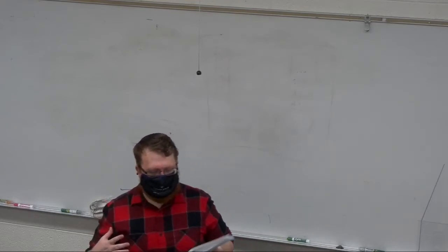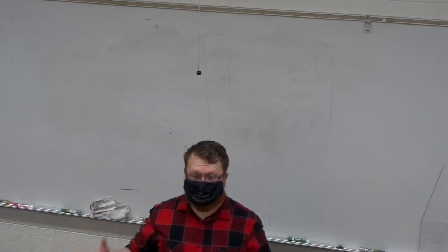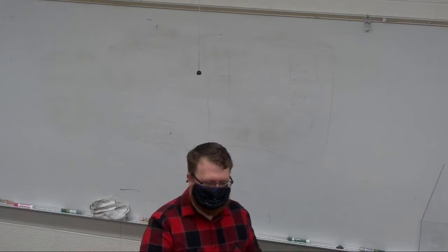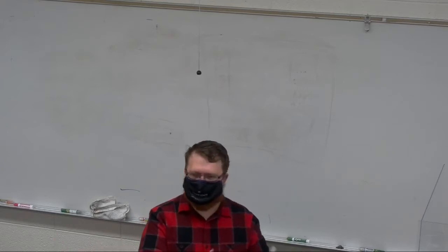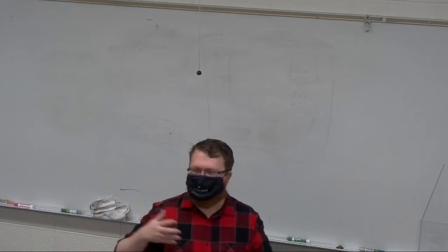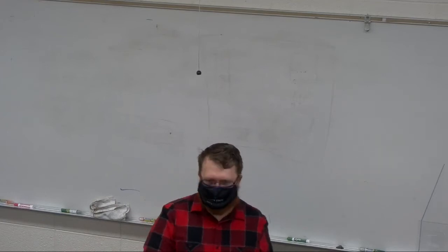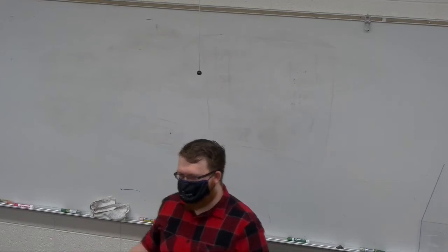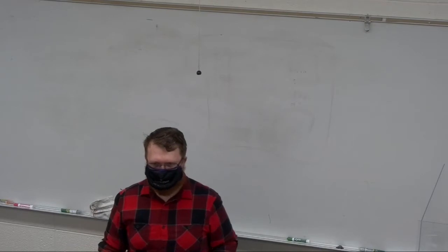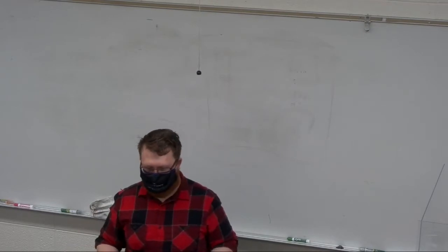These were called mask programmable devices in the early days. What that meant is they'd make a mask, which is a way of delivering charge to the circuits that they would then remember and stay configured. But you couldn't do anything to undo that, and the masks were very expensive. So it made sense when you were making 1,000 or 10,000 devices and then selling them as retail. But other than that, they weren't really practical for prototyping.